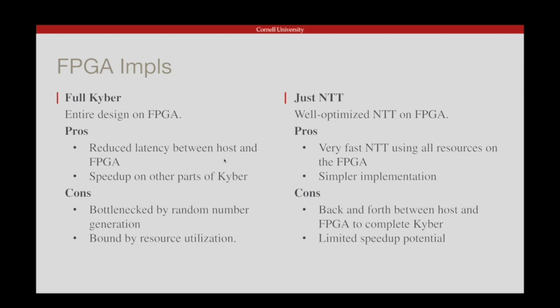The other implementation with just the NTT allows us to put a super well optimized NTT onto the FPGA. We can have all of the resources dedicated just for the NTT, and it's also simpler to implement because we don't have to transform all of the original functions into HLS. The problem, however, is that we will be going back and forth between host and FPGA to complete the Kyber algorithm, and this also limits our speedup potential because NTT only takes about a third of the runtime.